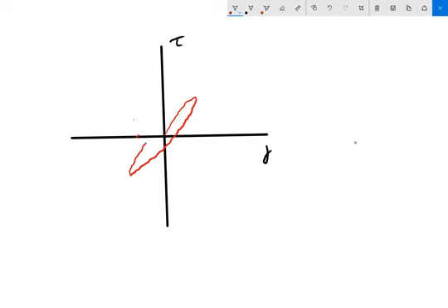we could see that the soil would kind of follow this type of banana type loop. And then if we loaded another cycle, it might look something like this. So what we end up getting is kind of this permanent deformation of the soil with strain.